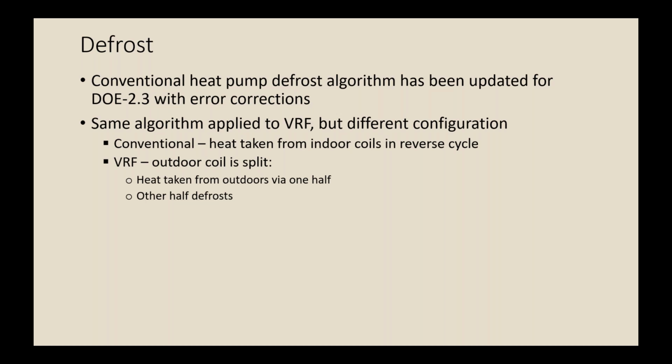When we looked deeply into it, we found that there were some errors in the conventional heat pump defrost algorithm that was being used in DOE 2.2. So we've corrected those errors and implemented that for conventional heat pumps and used the same algorithm on VRF systems.